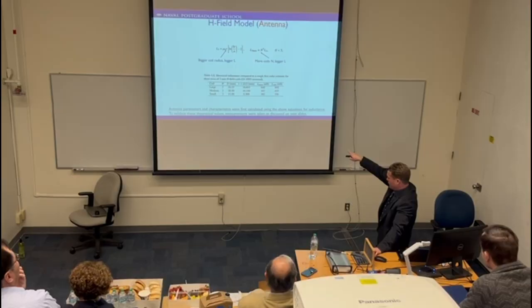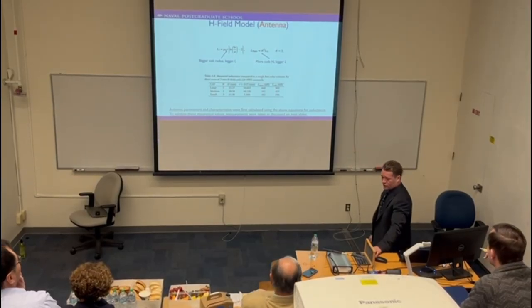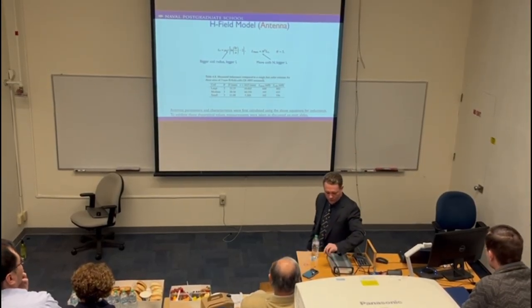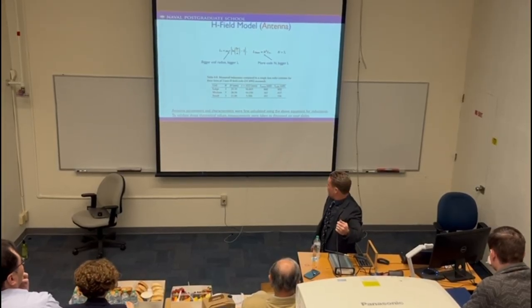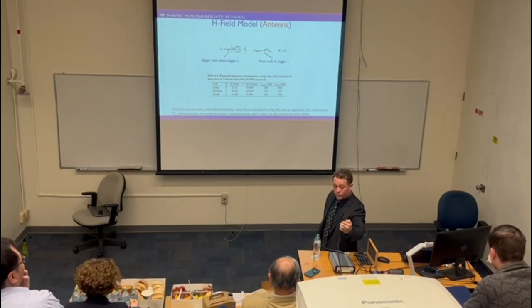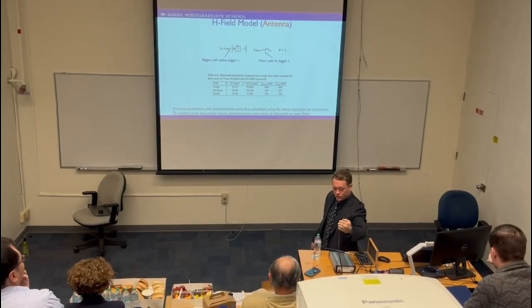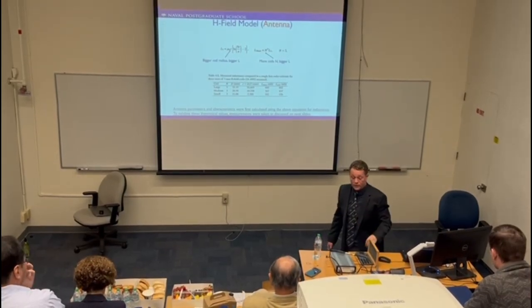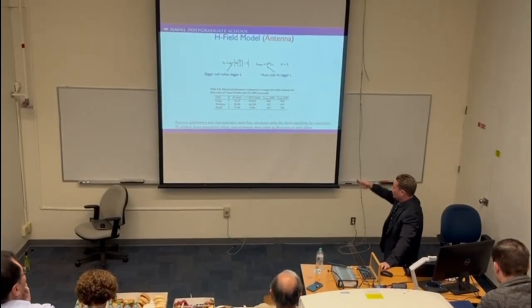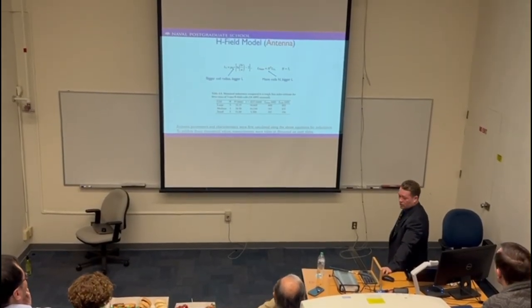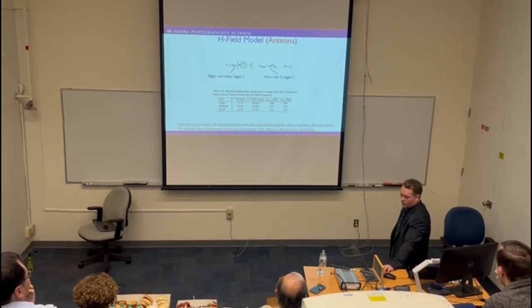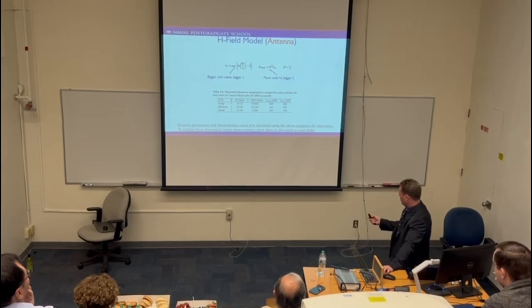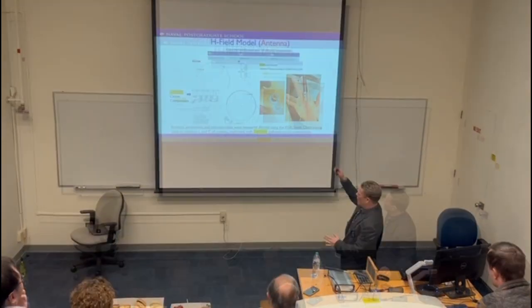I calculated these out and then actually started to go, and this is exactly, I would take port 1 of my VNA, do an S11 test, and essentially I was able to look at the Smith chart from this and determine what its actual inductance and capacitance were. Pretty close to the calculated, but I wanted to be a little bit more precise because I couldn't say that I precisely had, for instance, 20 millimeters all the way around. There's always going to be inconsistency. So I wanted to get a little bit more precision in what I was putting into my model. This is how I did that.